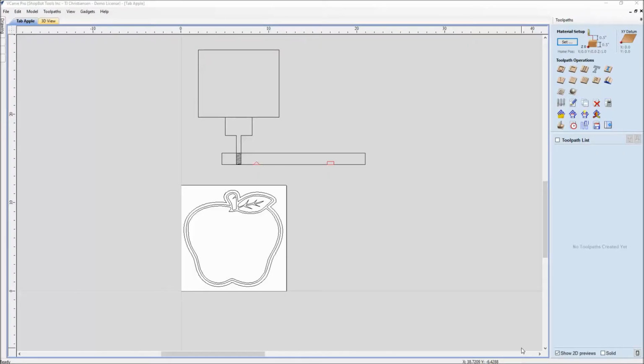Alright, before we get into setting up specific details, let's look at tabs and what they are, and where to even access them. I drew a little simulated version of looking down at your spindle. There's your cutter or your router, and here's your bit. You have the option of setting up a 3D or a 2D tab. To even access where you would do a tab is in the profile toolpath.